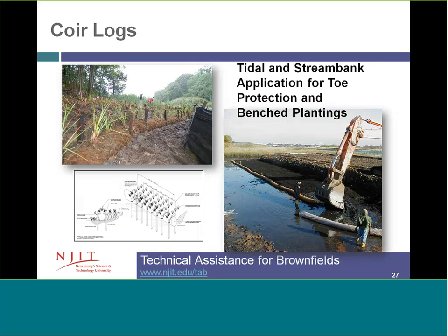This slide depicts the coir protection at the toe that I was discussing earlier. On the upper left, you see the coir installed and plants actually growing through the coir log, and then live plants up on the bank behind that. In the lower right, a similar situation, much larger coir logs, and that location is at the Fresh Kills landfill, where we created a tidal creek and then graded back the fill material to create a 3-acre tidal marsh.